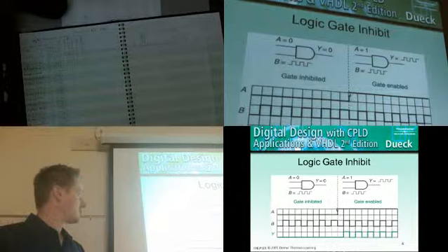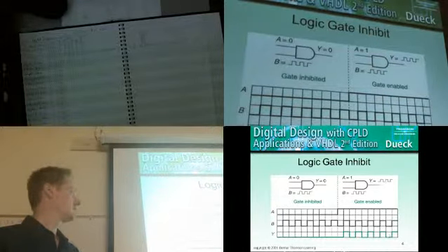When A goes to logic 1, now every time the B clock goes high, we're going to get a 1 on Y. So you can see that the waveform for Y and B are different, and really the waveform on Y is controlled by the signal on A.